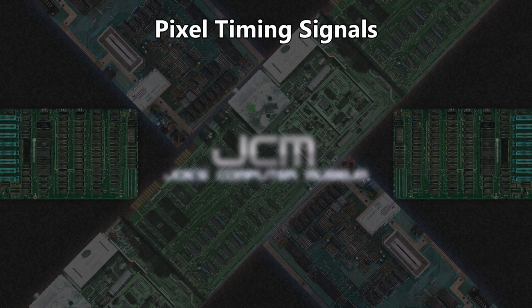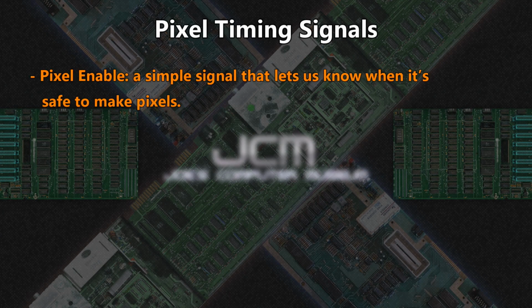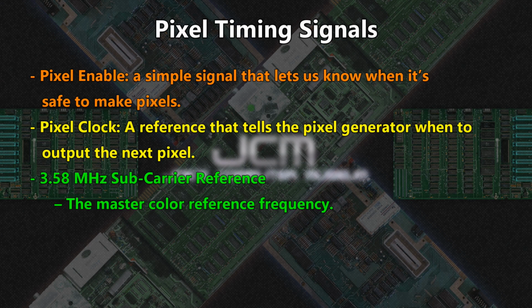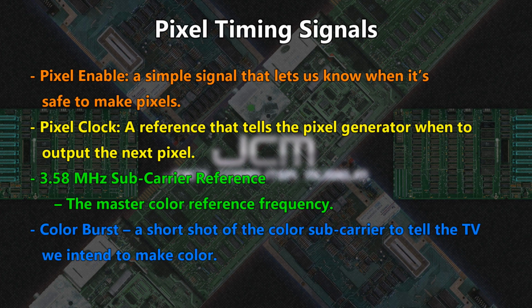Now let's get to generating new signals. These signals are Pixel Enable, a reference that lets us know when it's safe to make pixels. Pixel Clock, a reference that tells the pixel generator when to output the next pixel. 3.58 MHz subcarrier reference, the master color reference frequency. And Color Burst, a short shot of the color subcarrier to tell the TV we intend to make color.